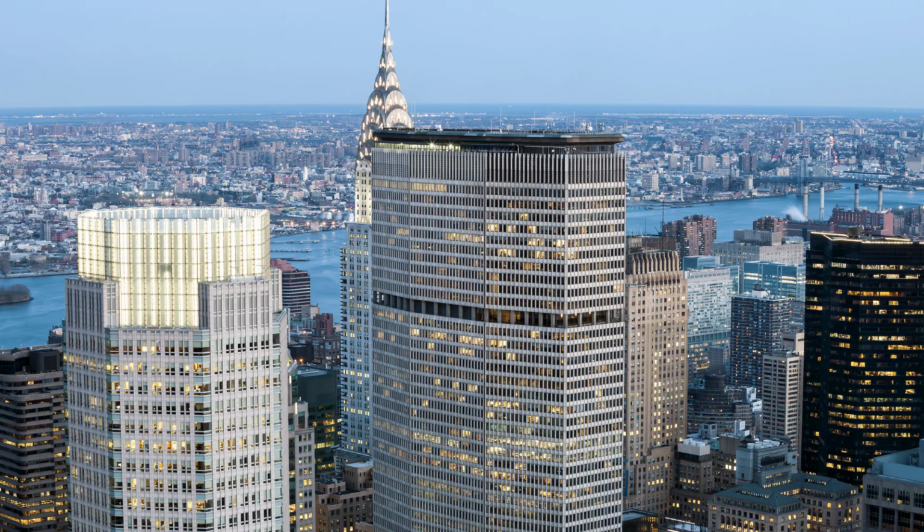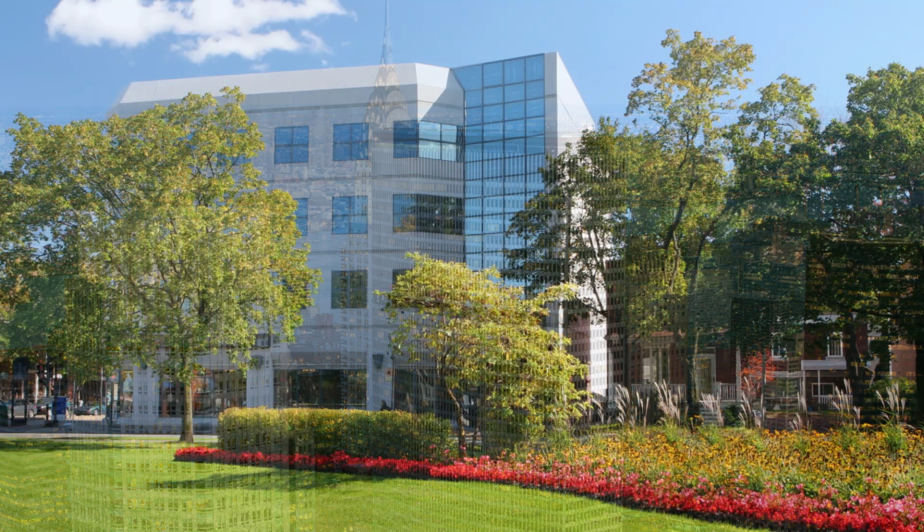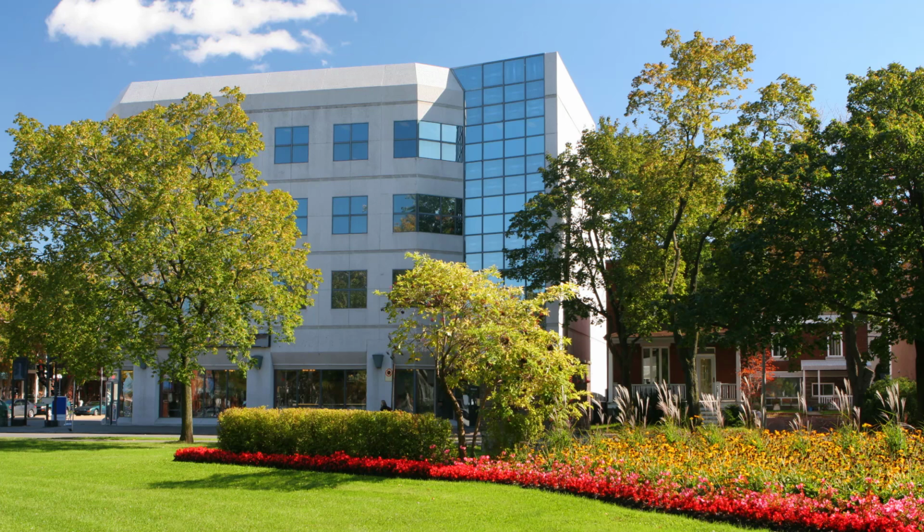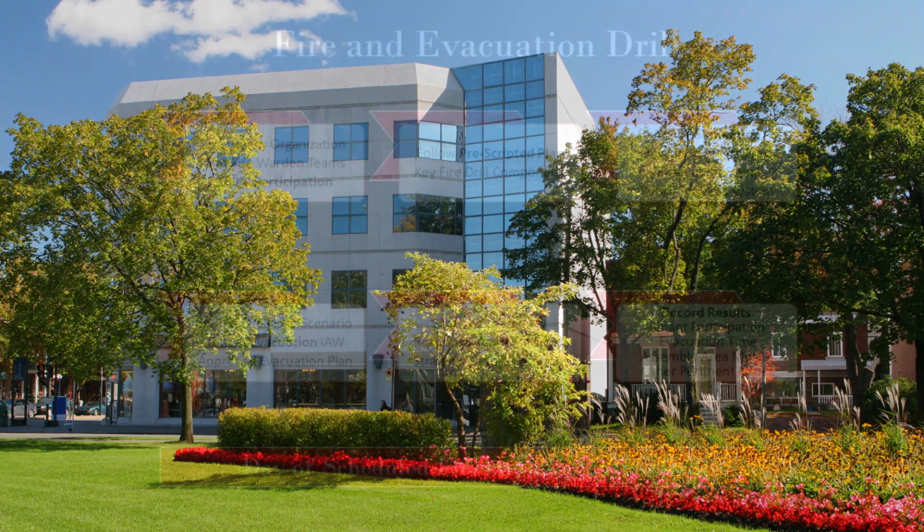In very large buildings conducting selective evacuation training several floors at a time, the fire and evacuation drill event may take a full day to complete in order to test fire alarm system design performance and occupant evacuation procedures as approved by the fire department. Most low-rise and mid-rise buildings practicing complete building evacuation should be able to conduct the fire and evacuation drill with test activation of one single fire alarm device.